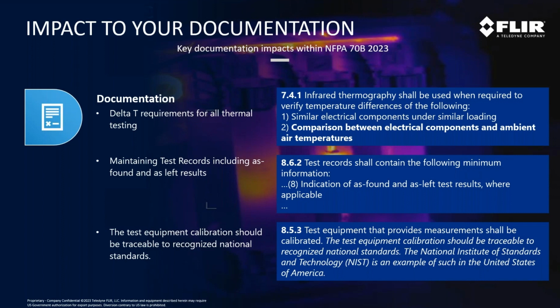So delta T, or temperature difference, is required for all thermal testing. And this gets back into that 7.4.1 section, but the comparisons between electrical components and ambient air temperatures, you have to pick one and stick with it, right? You can justify the change between either similarly loaded. Most organizations are gonna leverage the comparison of ambient.